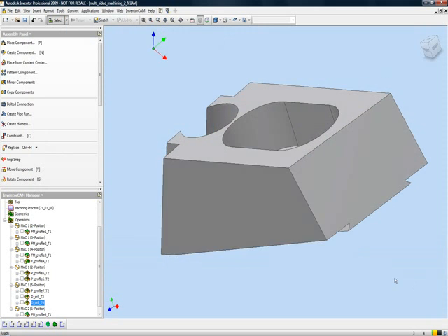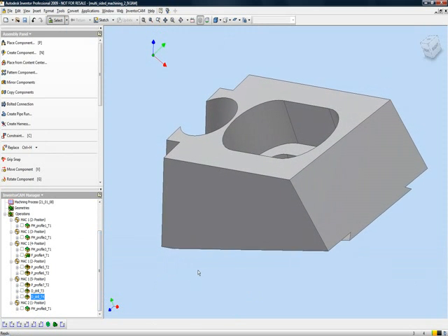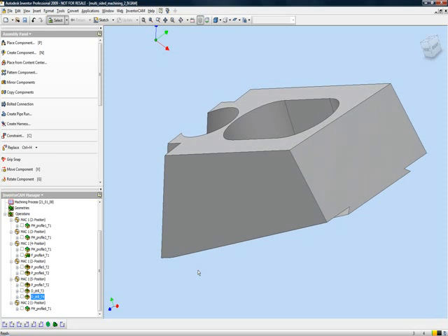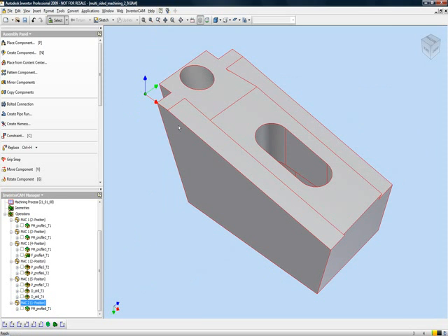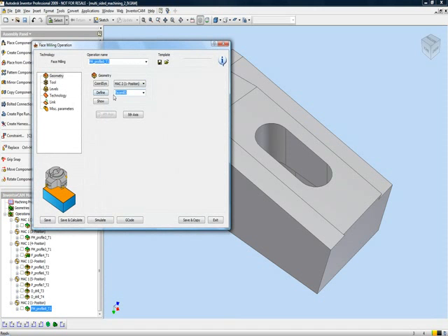Now in my last operation, I'll be basically finishing off the part by just simply putting it in a different holding, different position altogether. So we'll be using now Mac 2 position 1 just to do a simple face mill on the other side. And all I have to do is simply go to the operation, and what I've done here using my Mac 2 position 1, having my 16 millimeter end mill, and my technology area basically the exact same way I used my face machining before.